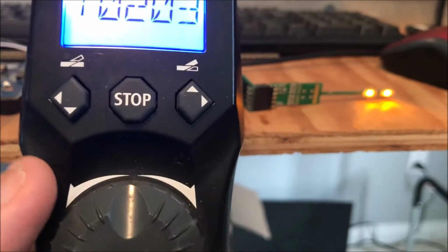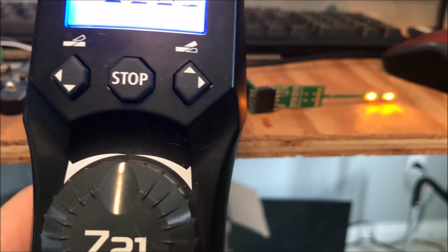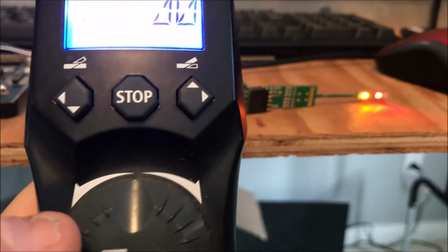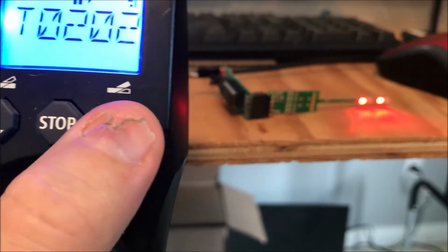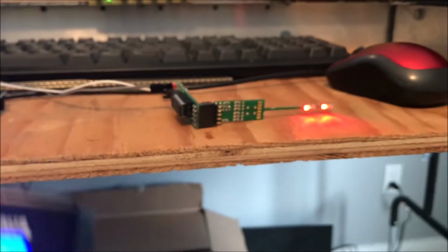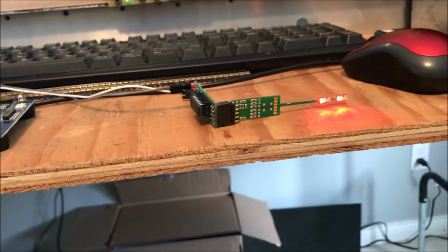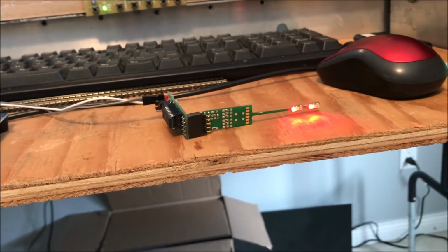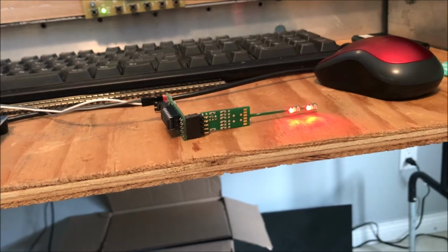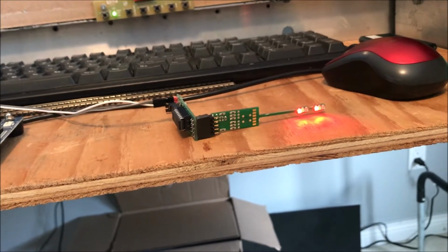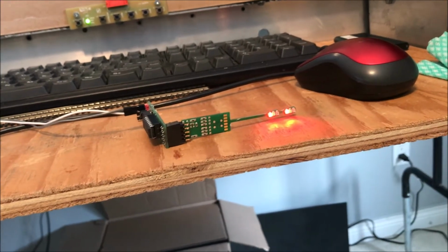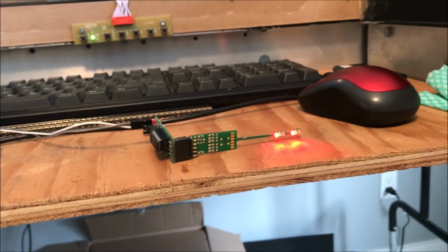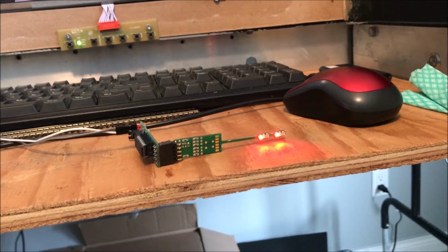So if I want them both to go red, I'll go 200 throw for the top one, and 202 throw for the bottom one. What happens is, it uses two addresses for each head: the red and green, and then the yellow and flashing yellow, and then the other one uses 2 addresses. So altogether, a single mast uses 4 addresses.